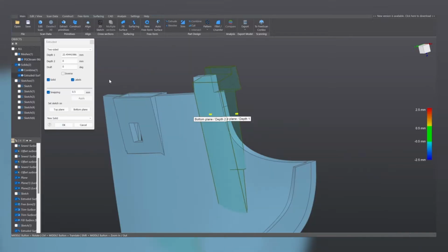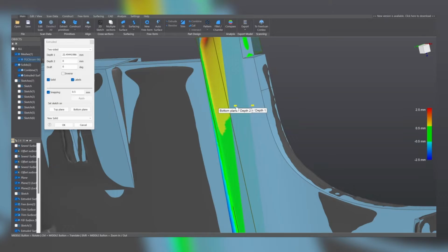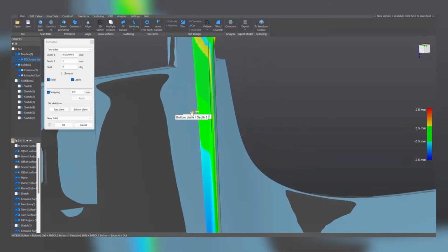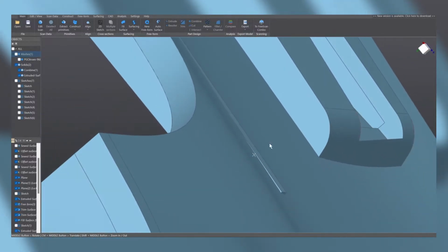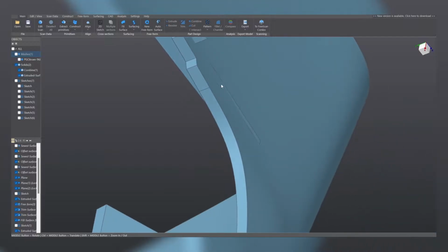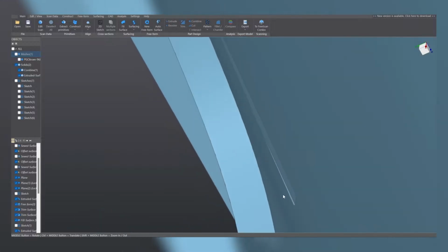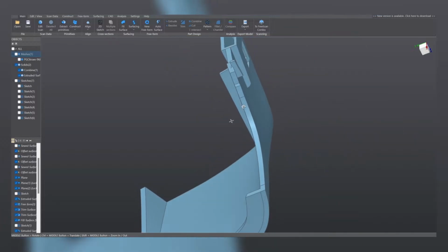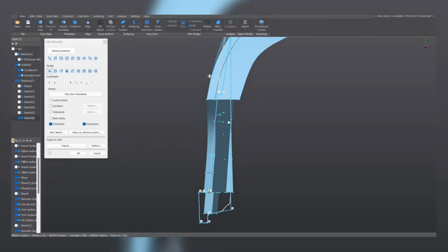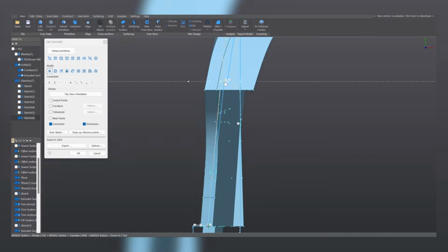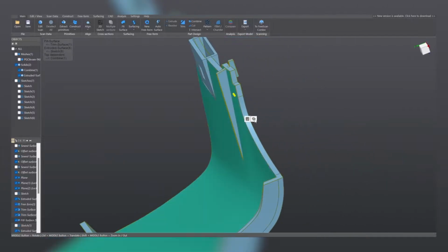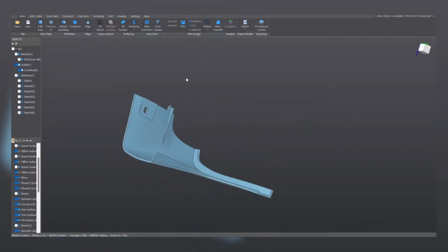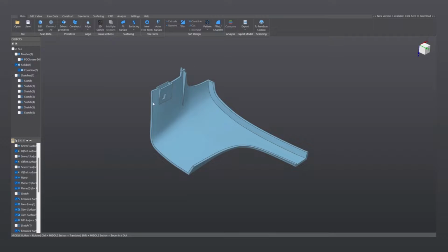Click on OK. Let's extrude it, let's display the mesh, and let's snap on these walls to define the extension of this extrusion. New solid is selected, click on OK. Let's hide the mesh, let's observe the result. Actually, I could correct my sketch a bit because the solid goes beyond, right? It's too large and it goes beyond the original body. So let's correct this. We double click on the sketch and we edit a little bit this line here, and now it's inside the body. So now we can choose both solids, combine them together, and that would be how we reproduce these prismatic shapes.